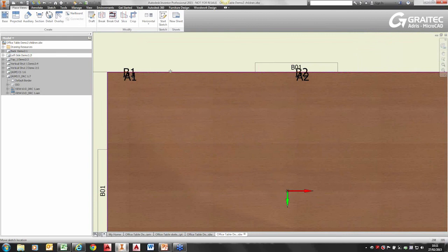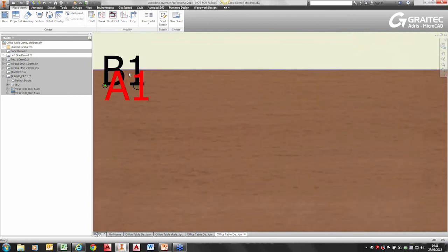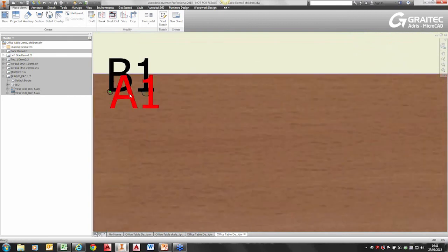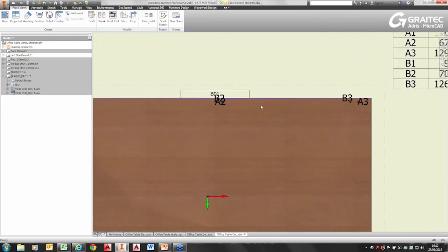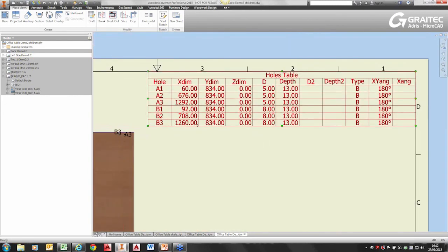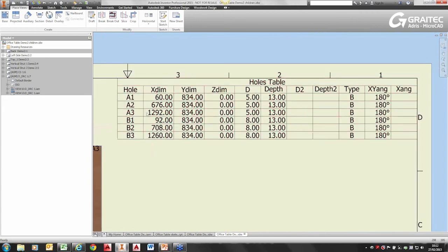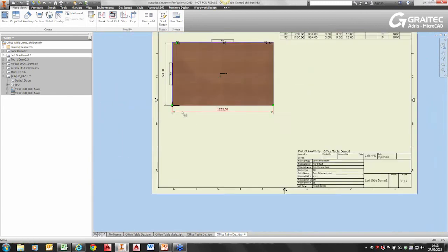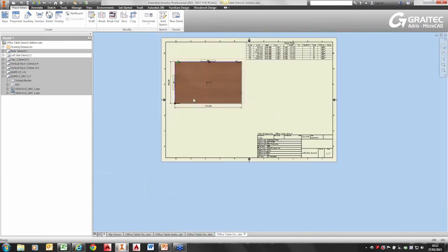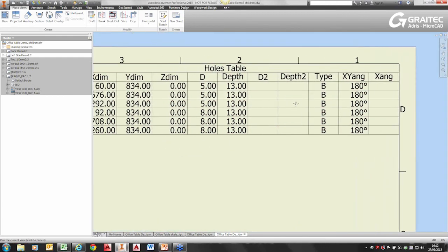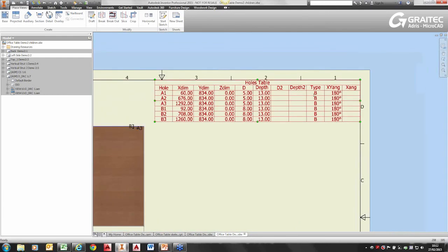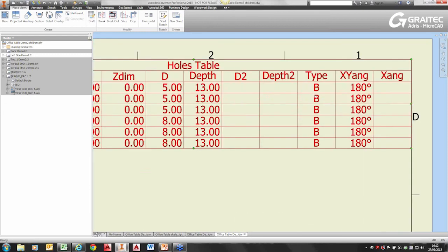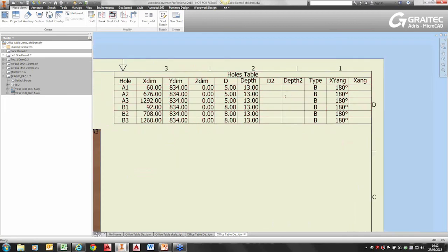This component here has holes in it. So you can see here it's given it a hole code. Again, you can move the holes, the coding around a little bit to get it in a more sensible place, make it clearer. And it tells us information about the hole. So it gives us the coordinate system based on the datum. It tells us if the hole's tight. So this is just a bored hole, a little blind hole, sorry, so it doesn't go all the way through.